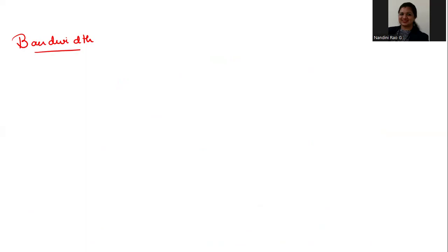Okay, so now here we have to find bandwidth. So what do you think here it might be? F naught is resonant frequency. Remember, okay? Resonant frequency is F naught. That's when you get the maximum amount of current. What is bandwidth? See here what we do. We consider half power. We want to know within which frequency our series resonance circuit works like an amplifier as of now. Okay? So we consider half power. So P by 2.